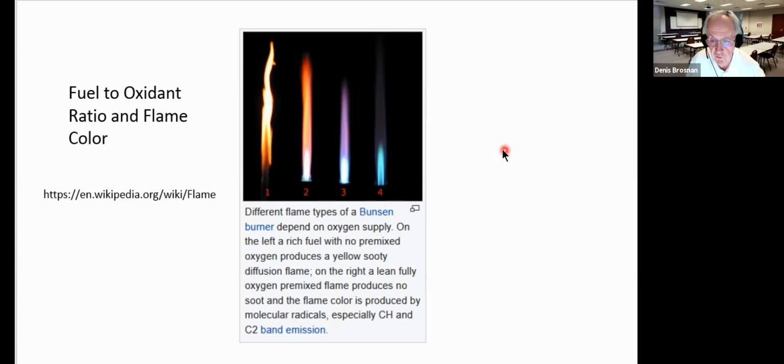As you get up as high as 1,700 degrees C or thereabouts, then the color of the light emitted from the furnace will be white light. So we can use color as an indication of what the temperature is in the furnace, and that's the basis for optical pyrometers. But nevertheless, we can also practically use color to think about the combustion stoichiometry, the air to gas ratio that's taking place.